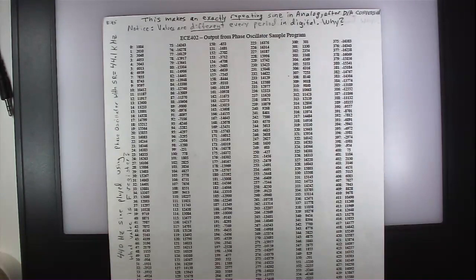Pretend you have your sine wave generator in the lab and you're trying to sample it. So you're going the other direction. You could try to adjust your frequency so that you get some sub part of the sample rate, a hundredth of the sample rate, and get 100 per period, maybe. You'll never be able to twist that knob accurately enough to really hit it. It just doesn't happen. And similarly, when people play music, they're not going to hit exactly that frequency. It's a non-starter.